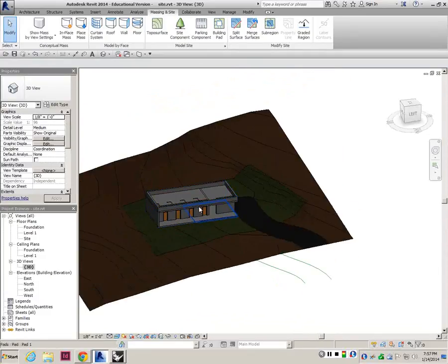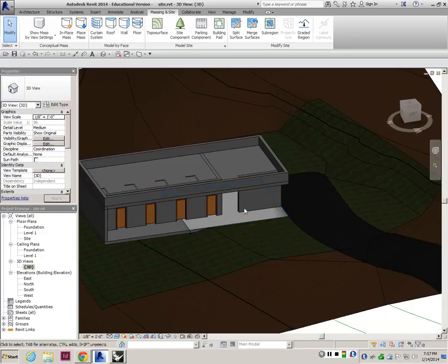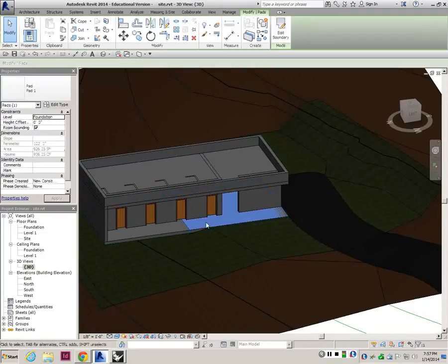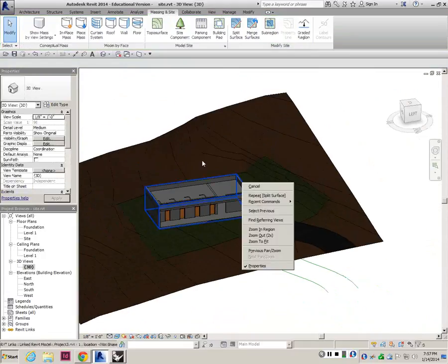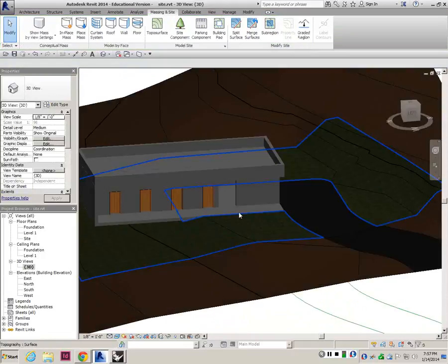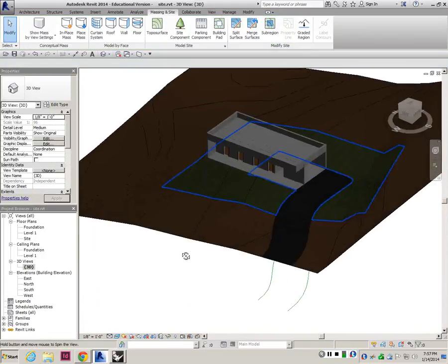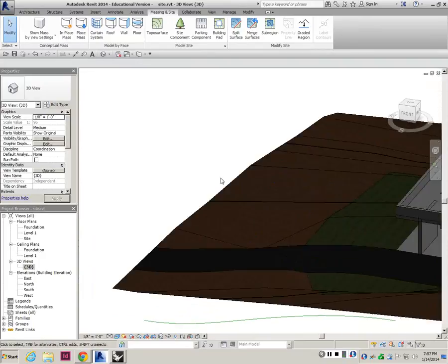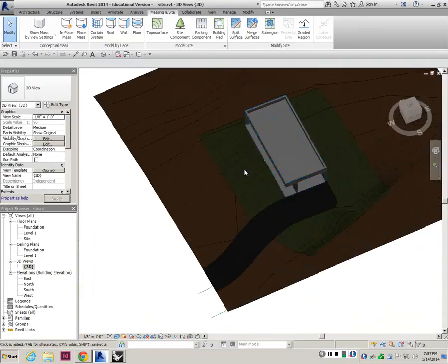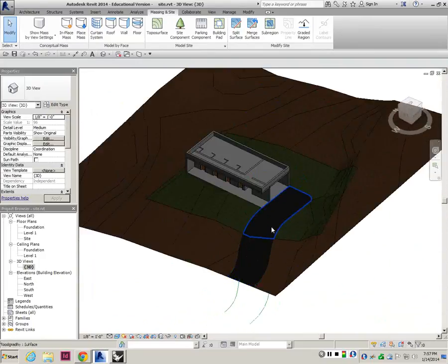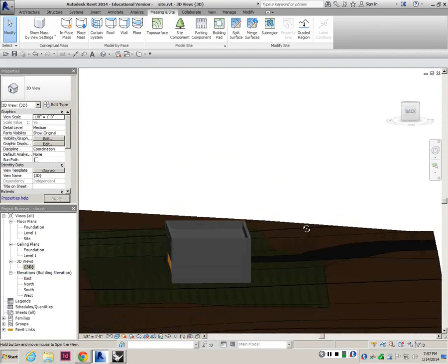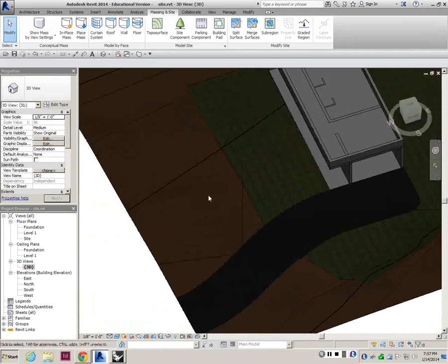Let's do shade it. It doesn't show the materials, it only shows them in realistic view, but basically they are there. Okay? And the building pad is, if you look at it, located at the same level as our foundation, but we could put it at -1. It's just a tool to define the foundation for our building, so that will create a nice model there. Okay? So that's kind of how you can create roads as well, do kind of topography modeling.